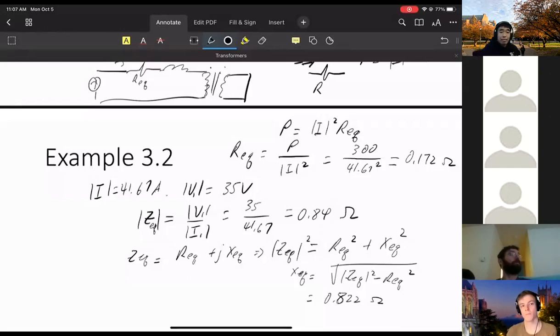Very easy. You take a meter, plug it in there, and you read the sinusoid out of it. You basically measure the max to the mean for a few cycles and take an average. That's your magnitude. Power is measured as an average quantity. Similar with current. Phase is hard because to measure phase, you need a reference.